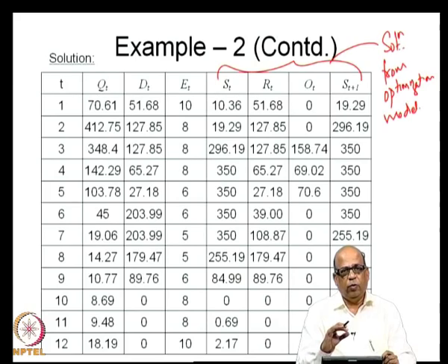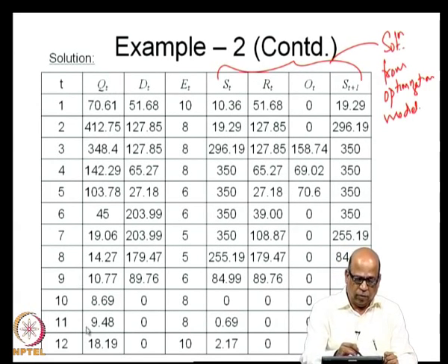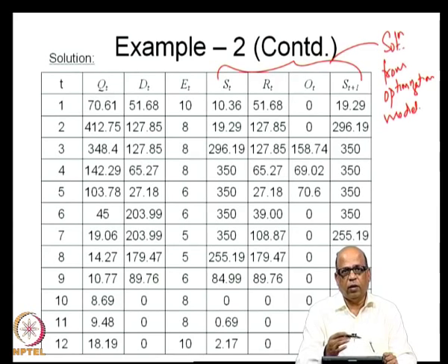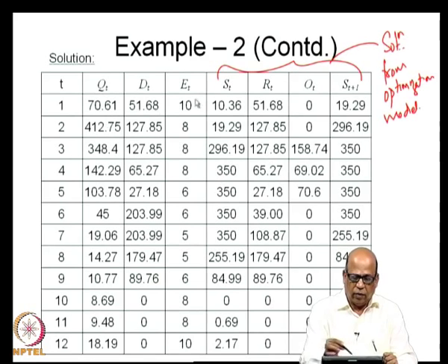How do we communicate the policy to the operators? By saying that on an average in a year, you have this kind of inflow pattern. Now, these may be average inflows for the different time periods, June, July, etc. For these kind of average inflow patterns, you maintain these reservoir storages 10.36, 19.29, etc. and make these kind of releases as the flows come.